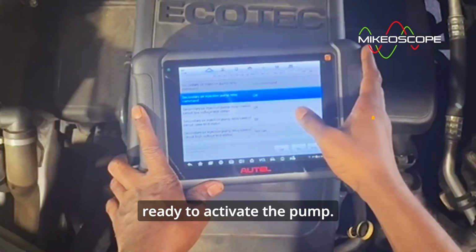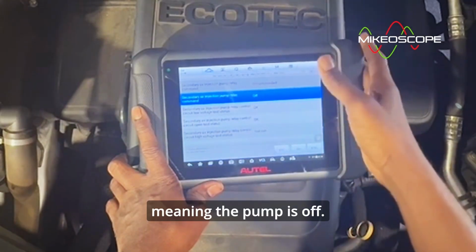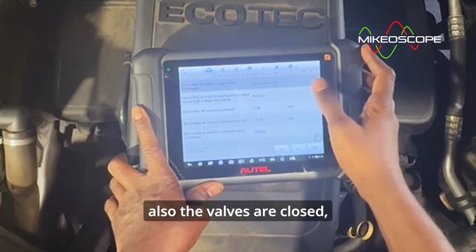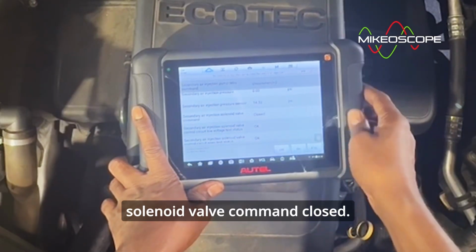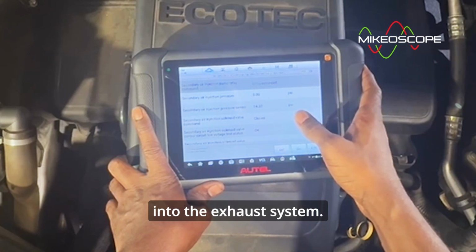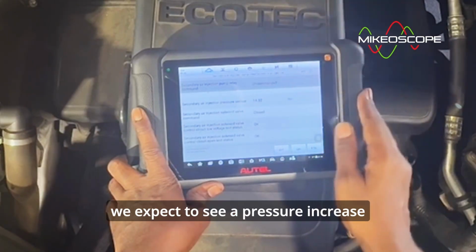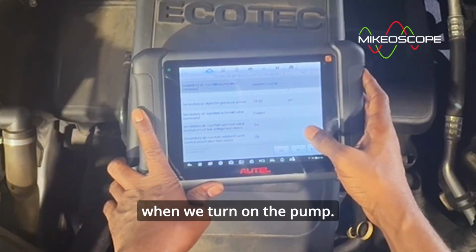All right, so we're ready to activate the pump, and I just wanted to show you guys. So here, the pump relay is off, meaning the pump is off. You can see here also, obviously here it says off. And then you can see also the valves are closed, secondary injection solenoid valve command closed. The valves are normally closed, and they only open when you want to vent fresh air into the exhaust system. And the secondary air injection pressure is 0 as well. Now, remember, because the valves are closed, we expect to see a pressure increase of about 2 to 3.6 psi when we turn on the pump.